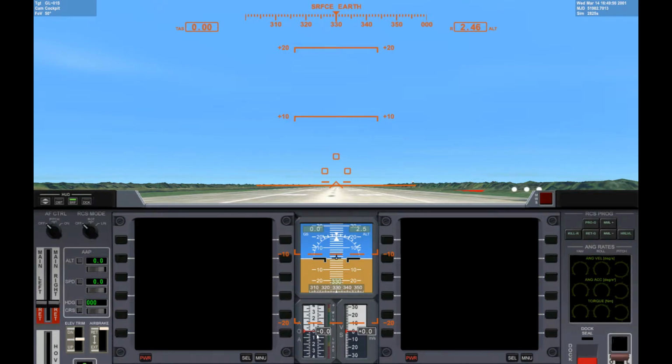Okay. This is your angle of attack indicator. This indicates how close the front of the nose is with the airstream. A high angle of attack can be dangerous. It can cause spins, it can cause excessive heating, it can cause stresses. It can be bad, but it's not always bad.